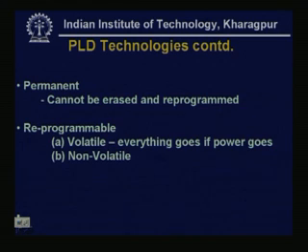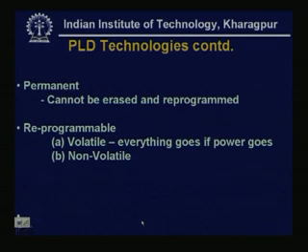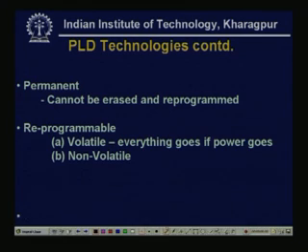So, though we are calling this a programmable logic, the programmable actually means that only the hardware is available and only one time we can program the device and we will get one fixed design. Now, reprogrammable ones are volatile or non-volatile. Volatile means everything goes if power goes. If we use a volatile memory, here we are using the lookup table, so what type of memory the lookup table is implemented with matters.